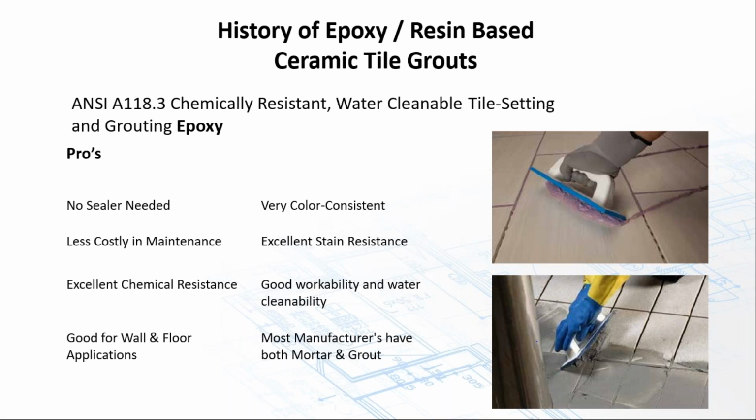Most manufacturers have, if needed, epoxy mortars along with the epoxy grouts. A lot of times epoxy mortars will be used when there's a heavy need for more acid resistance. For example, in a dairy or winery or brewery, because of the acids that are produced from these products, not only will you use an epoxy grout, but you'll set the quarry or the pavers with an epoxy mortar also. So it all locks together, bonds together. They do have, like I say, good workability and water cleanability. They're a lot easier to work with than what they were years ago.